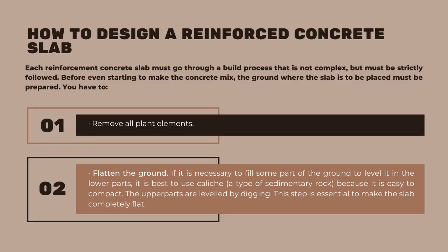How to design a reinforced concrete slab. Each reinforced concrete slab must go through a build process that is not complex, but must be strictly followed. Before even starting to make the concrete mix, the ground where the slab is to be placed must be prepared. You have to: first, remove all plant elements. Second, flatten the ground.